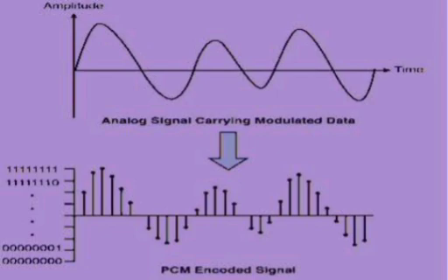Phase shift keying. In phase shift keying, the phase of the high frequency carrier varies in accordance with the digital data 1 or 0. NRZ signaling is used. Bandwidth requirement for PSK is bandwidth equal to 2 into bit rate, that is 2 RB. In the case of PSK, probability of error is less and SNR is high. Mainly used technique in wireless transmission.